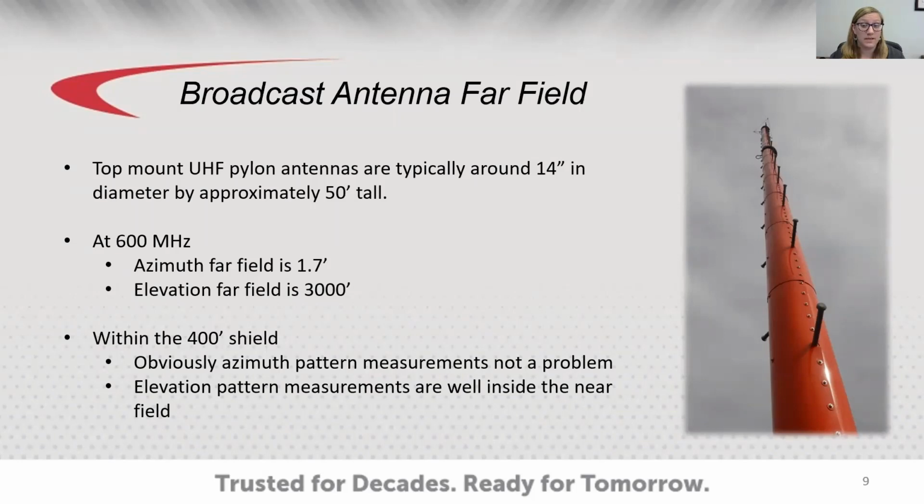So if you were to measure this antenna with a drone inside the 400-foot shield of the tower, you would have no issues measuring the far field azimuth pattern. The elevation pattern measurement, on the other hand, would be well within the near field of the antenna.